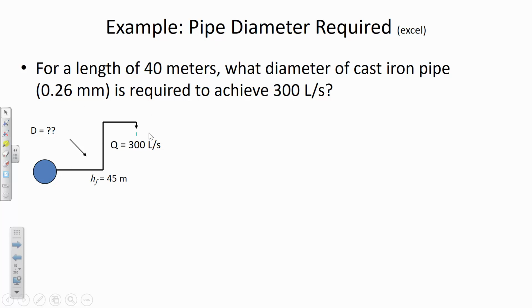You're close, because here it's just discharging to an open valve. If it was enclosed, it would be not enough pressure. But here it's going from whatever the pressure is to 0, so the pressure gradient's going to be the same, but the flow rate wouldn't be high enough. It's just like trying to fill a pool with a garden hose rather than a firefighting hose. If the hose is too small, you've got all of this pressure trying to drive the flow through a really small diameter, and you just can't achieve the same flow rate as you'd get if the pipe diameter was larger.